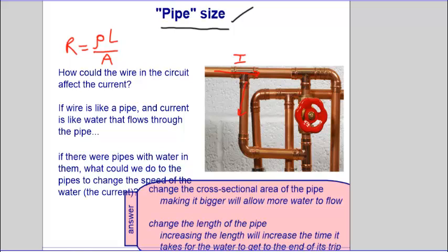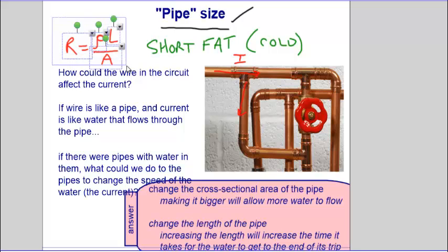And the easiest way to remember this: wires with short resistances like it short. That means a small length. And the second thing they do, a big cross-sectional area. They like it fat. And then a sidebar thing, wires also like it cold, but we don't account for temperature in this formula. So we'll use this formula. I'm going to highlight it. So let's just highlight everything.